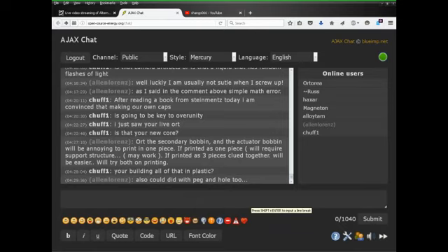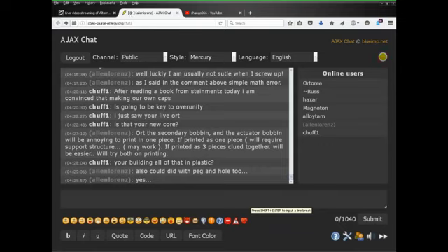Yeah, a peg and hole. Yeah, so they lock together like Legos. You know, like Lego bricks where they've got a little plastic pin on the top and a little plastic hole underneath. Yeah, you could do that, and then I could just press the two halves together. Yeah, that would work, and that would make sense. It would make it a lot easier to mould as well, because if I want to make duplicates in resin, for example, it would be a lot easier to cast it in a mould.